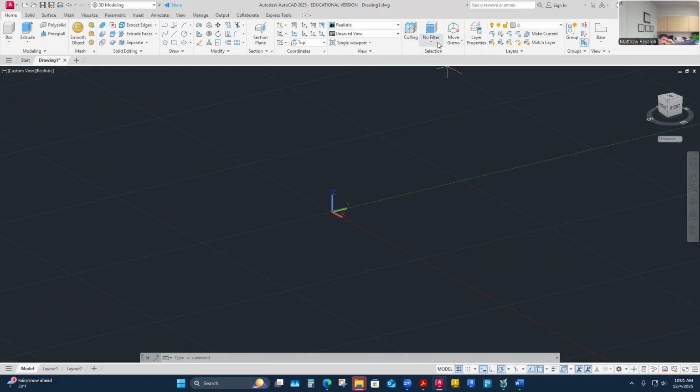I've got a new palette, a selection palette. Layers is the same, so this is just our normal standard layers palette. Of course, this is a new template, so it has nothing. It's just a dumb template. It only has layer 0, so it goes with anything. Usually I like to have layers to draw on because I can draw stuff and use them for construction. For 3D drawing, I need similar layers as for 2D drawing. I need construction, text, and dimensioning abilities, so I need all the same layers.